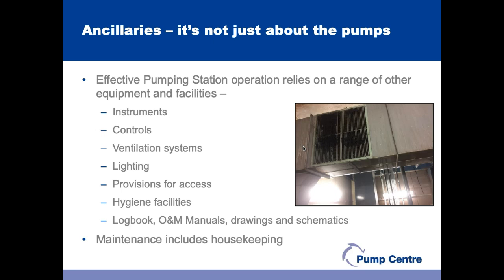We need to make sure that the logbooks are updated, and anybody who's going down to do some work has access to operation and maintenance manuals, drawings, and any schematics. A lot of those you would classify under housekeeping, but what I'm suggesting is that the maintenance really needs to take account of those things, not just focusing solely on the pumps.